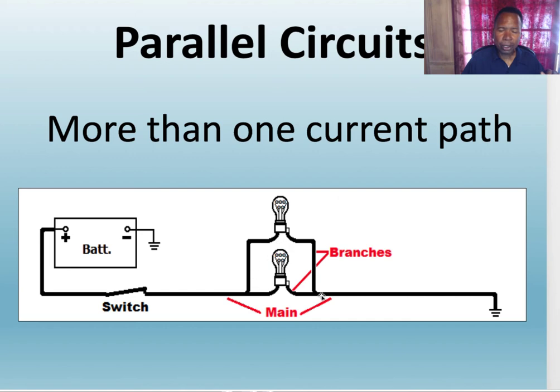They're going to pull a different current based off that resistance. If this was 2 ohms, it will pull 6 amps. If this was 4 ohms, it will pull 3 amps. It's not a series circuit anymore, it's a parallel circuit. So each leg will draw a certain amount of amperage, or different amperage, based off its resistance.